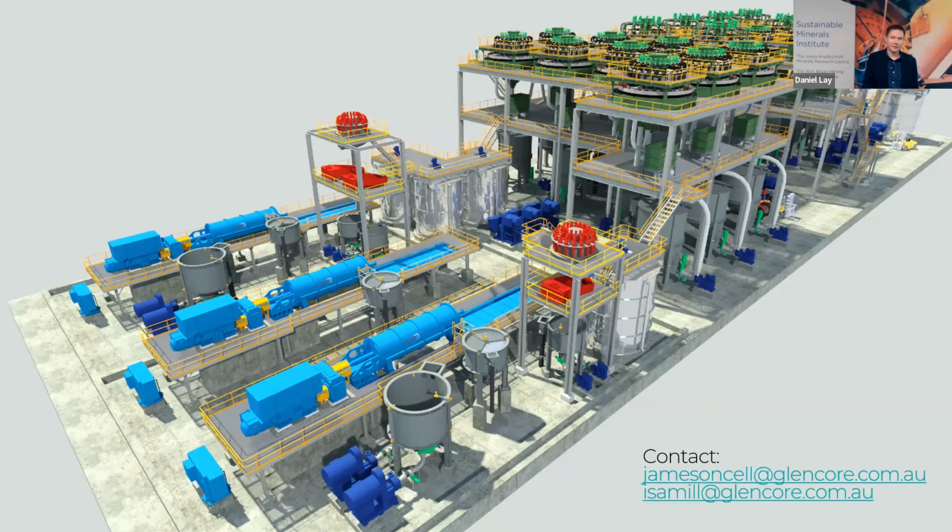Now, if we were to go to, say, an L50, a very small Jameson cell, you would start to battle with some practical things: wall effects, getting the slurry jet to be exactly vertical so that it doesn't hit the wall. There would start to be some practical constraints with running continuously through that unit.